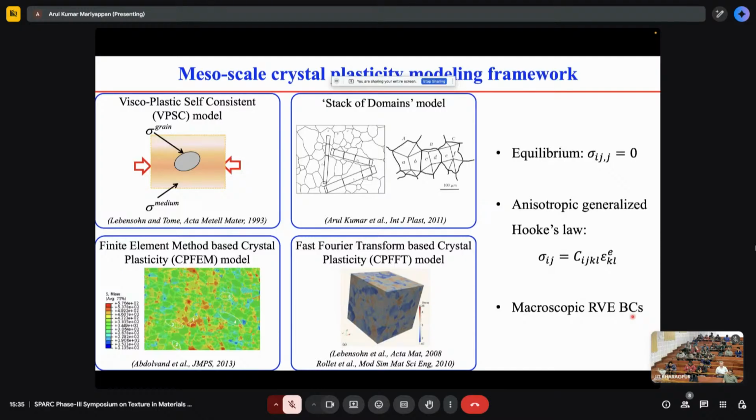So we can choose any framework, but what do we need now? How to establish this relationship, that is, the generalized Hooke's law. That is the place where we have what is called the constitutive model. That constitutive model is supposed to be mechanistic, physics-based, and sensitive to the microstructure. We'll see how in our team we are developing the microstructure-sensitive constitutive model to establish this generalized Hooke's law.